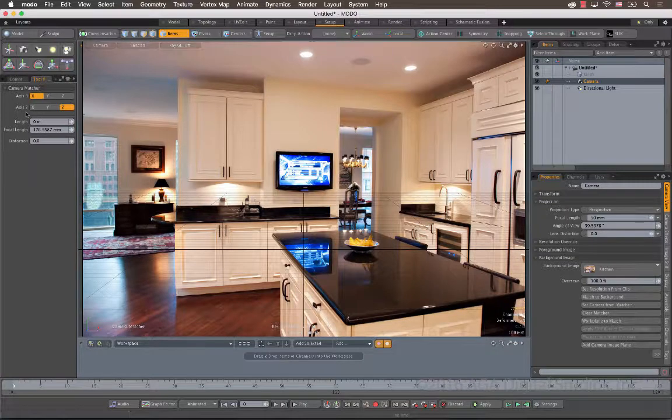You see Axis 1 and Axis 2. So in order for this to properly work and properly align, you want to have two lines drawn for your Axis 1 and for Axis 2. In this case, we're going to choose the most perpendicular. Basically, give the most information we can to the image. In this case, I've got pretty good X and pretty good Z working here in this image. So with the X for number 1, we're just going to click, and then we're going to drag out, and we're just going to line that up, and I'm going to use the edge of the counter.